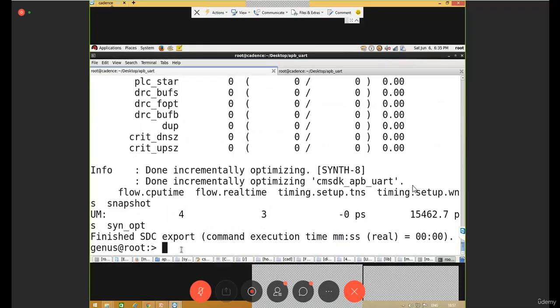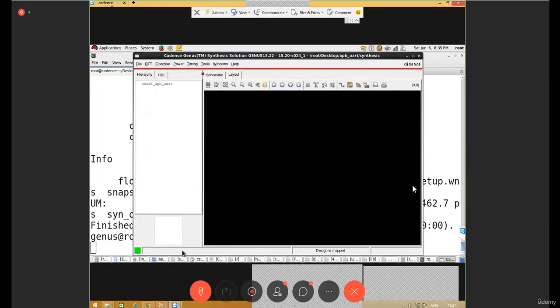Okay, so this is the GUI window here, and here, if you can see, you can get the design name. Right-click on it. You can use open in schematic viewer main or schematic viewer new, and you can see the gate-level netlist that has been created. So this is basically the GLN in schematic form. If you can zoom and see,